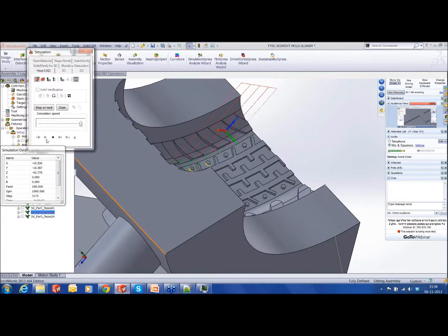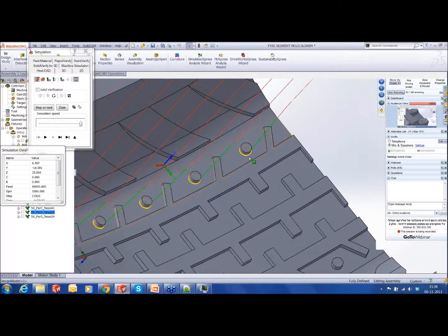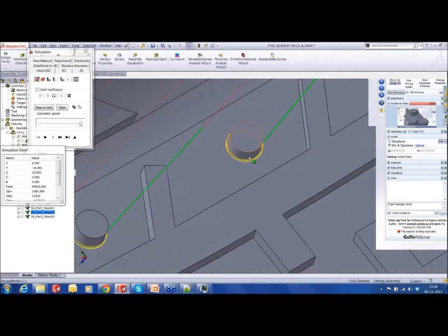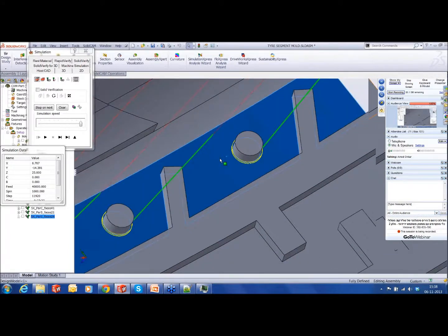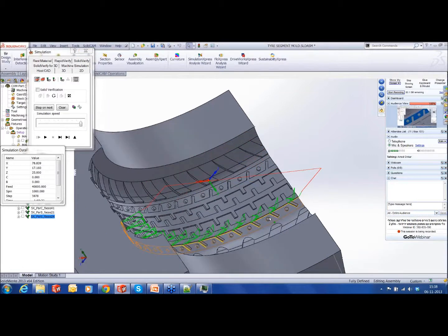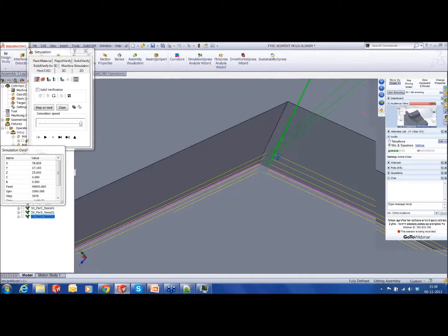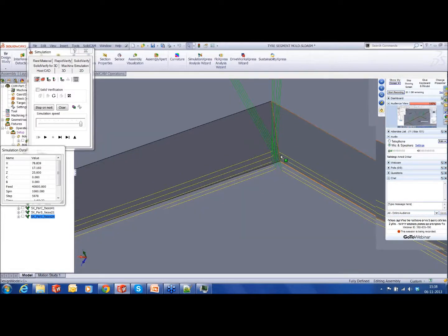This is for generating the sharp corners for these projections, exactly the way we did earlier for the earlier part. And to end it, I've done a parallel to surface again to machine the same corners. And you can look at what happens here. When it goes into the internal corner, it's retracting the tool out, changing the tilt, and coming back again to that area to continue machining.